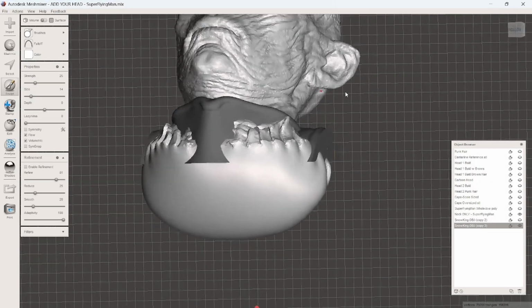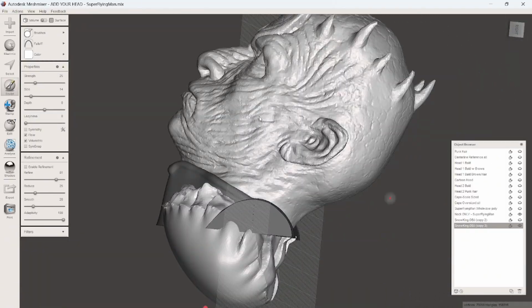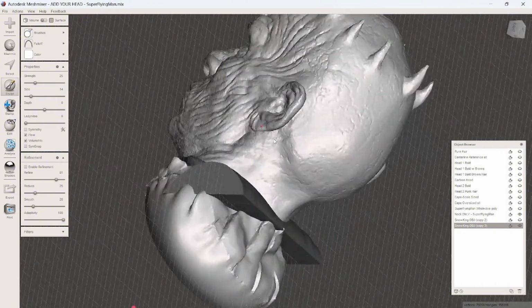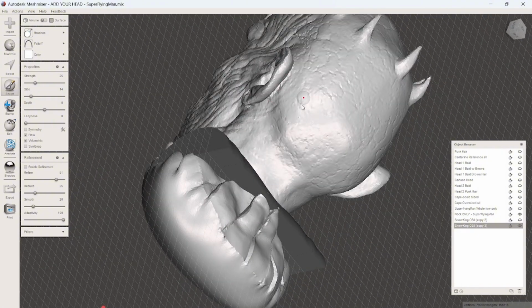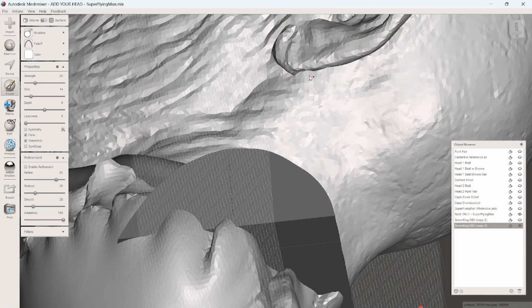So I could soft transform his ear a little bit to get his ear to print, but then it would make his ears look like an elf. Now what I do is I make another object that'll go inside of his head, and it'll fill in behind his ear, and then I merge the two objects together. But I could also sculpt this and bring this out so that his ears will print correctly, because there's too big of an overhang right there.